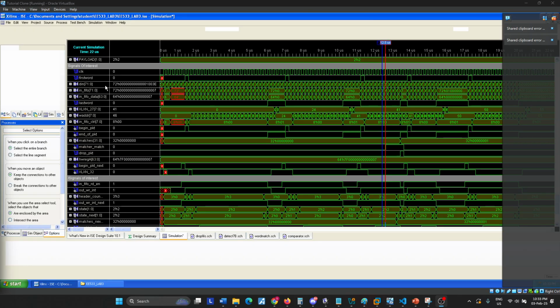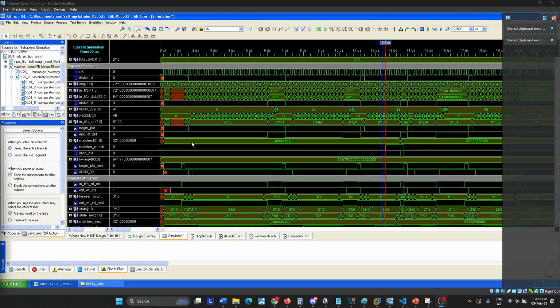On the screen, you will see the simulation waveforms for the particular circuit that I just showed, which is essentially the input FIFO, the 7-byte pattern matcher, and the drop FIFO. All these signals are of interest, so let's go into some of the signals that we require. The first one will basically tell whether the packet entering the pattern matcher is the first word of the packet or not. The D input is the input from the test bench into the FIFO. In_FIFO is the actual signal of interest where the pattern matching starts.